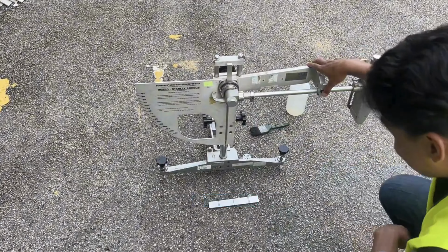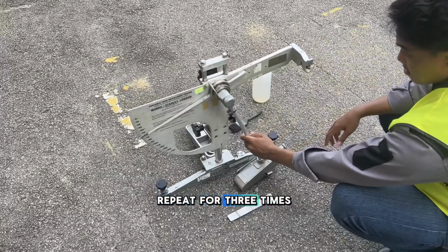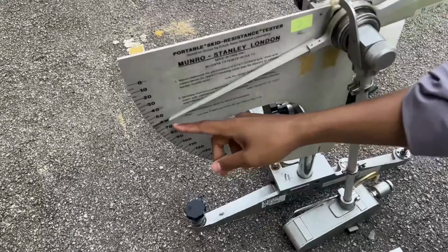For the dry condition, push the release button to allow the pendulum to swing and record the reading. Repeat 3 times to get the average value. For the wet condition, evenly wet the test surface with water. Then repeat the pendulum release and record the readings. Take 3 readings and calculate the average.